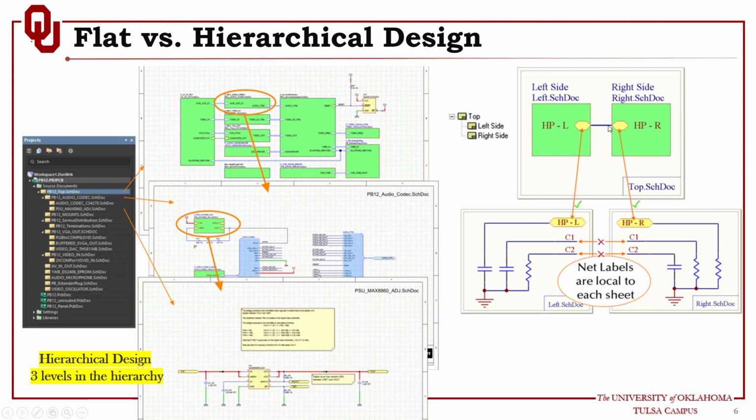And the parent sheet includes wiring that carries the signal across the sheet entry in another sheet symbol, as you can see in here. So this is one schematic sheet, and this is another schematic sheet, and the nets in this schematic and that schematic are connected through ports, and this port is referenced through a sheet entry which has the same name as the port, and now you are transferring this net from one schematic sheet to another schematic sheet through a wire connecting the sheet entry on the first sheet symbol to another sheet symbol.